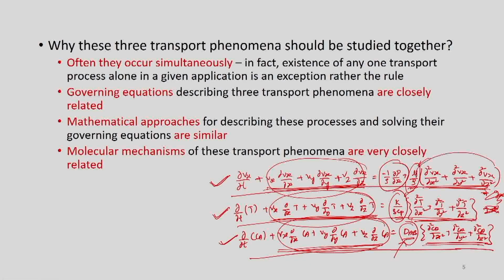And these mechanisms, the viscous component here, then the heat conduction part here and then the diffusion part here, these are due to molecular mechanism, whereas the convection terms are due to the bulk motion. So the viscous terms, conduction terms and diffusion terms are because of the molecular mechanism and they are dependent on the properties of the material.